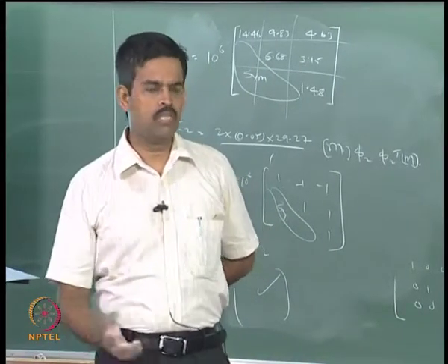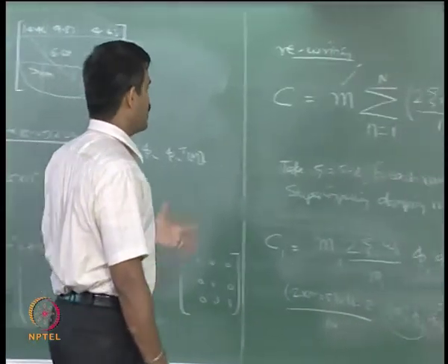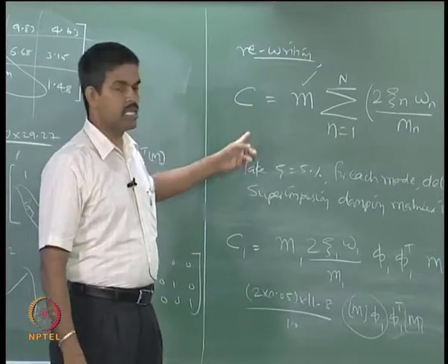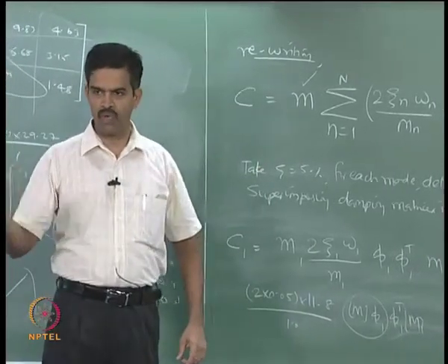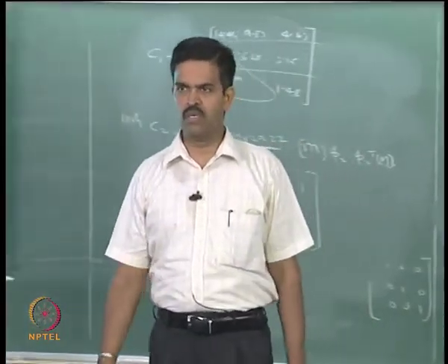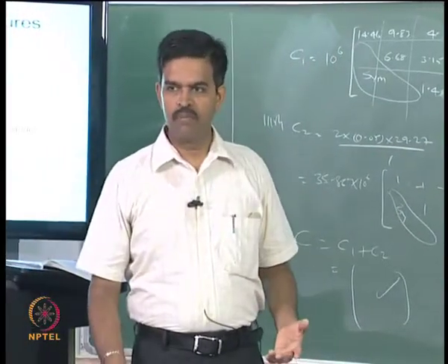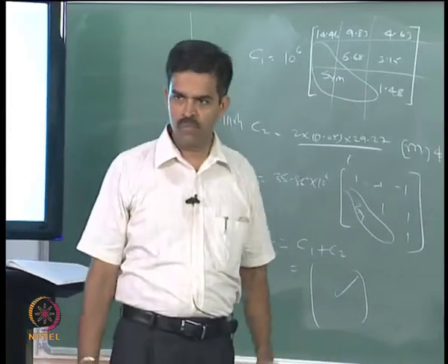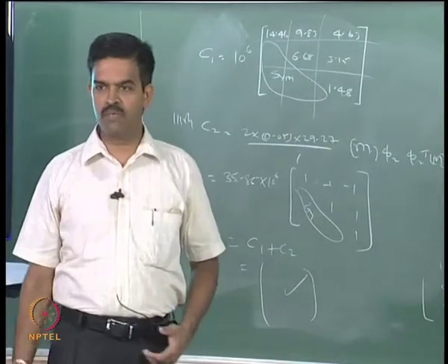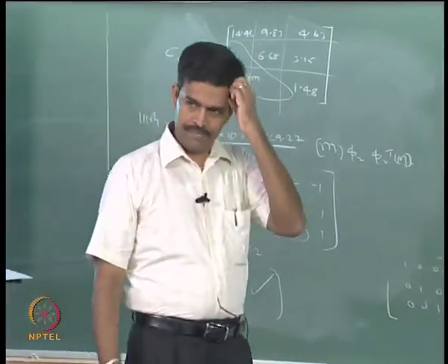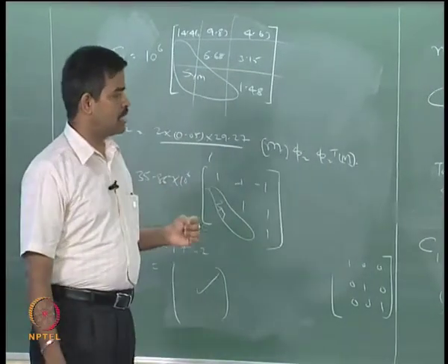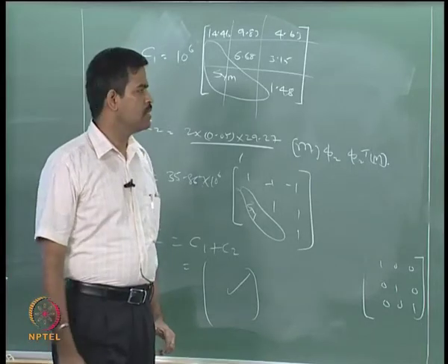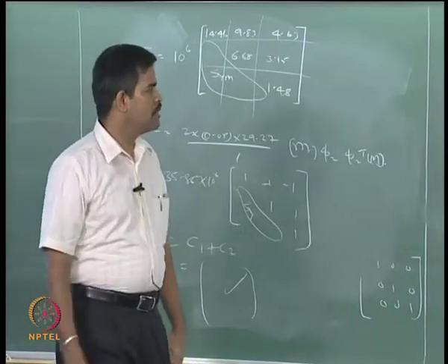Okay. So, now let us believe that ideally speaking I can include all the modes here. Caughey had this problem. When you talk about C or zeta, it was skipping at omega 1, 3, 5, it was skipping in between some certain frequencies, is it not? But here you may not have to skip, you can continuously add all the damping ratios in all the modes and find the C matrix here. So, that is, you can say, a different version of C matrix compared to Caughey. Of course, we understand Caughey series is an improvement on Rayleigh damping. Okay. So, Rayleigh damping is a fundamental model of reference what we have here.